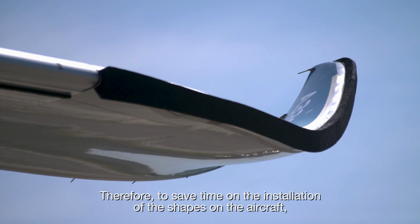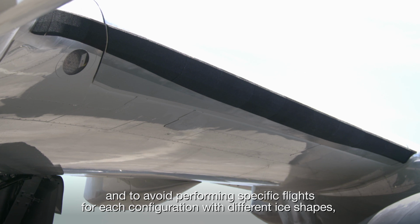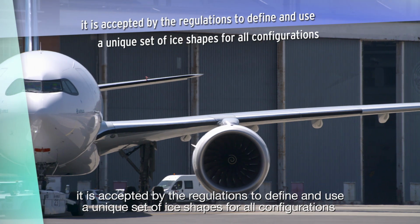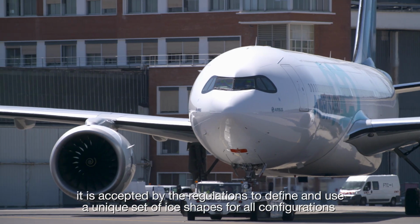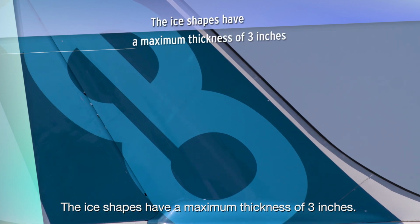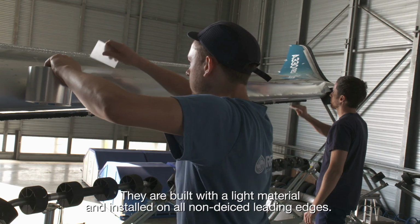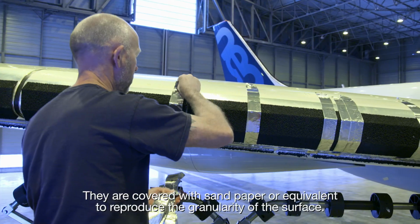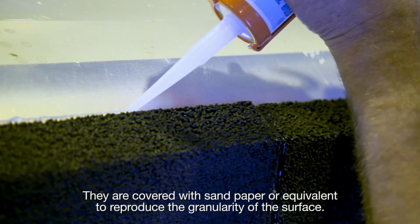Therefore, to save time on the installation of the shapes on the aircraft and to avoid performing specific flights for each configuration with different ice shapes, it is accepted by the regulations to define and use a unique set of ice shapes for all configurations, covering the most critical situation in all cases. The ice shapes have a maximum thickness of 3 inches. They are built with a light material and installed on all non-de-iced leading edges. They are covered with sandpaper or equivalent to reproduce the granularity of the surface.